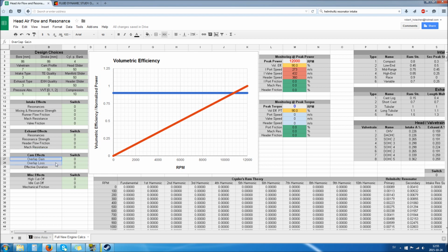Anyway, so at low RPM you have overlap losses if you are revving too low, and you have gains for overlap where this stuff actually works, where there's the correct timing for the intake charge coming in and pushing out the exhaust, and the exhaust pulses being sucked out and dragging along the intake into the cylinder. There's a lot of weird magical things going on which require very exact timing to actually work. So you get different resonances at RPM depending on your cam profile.